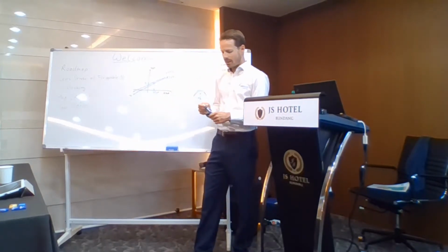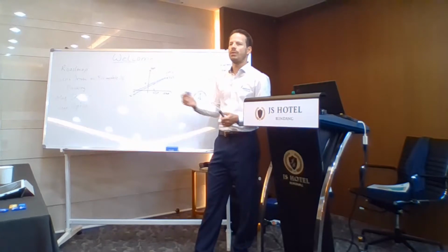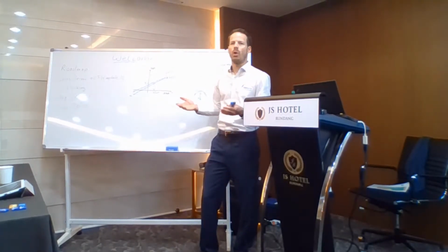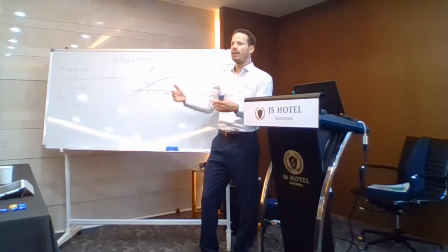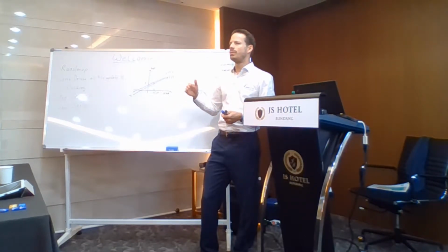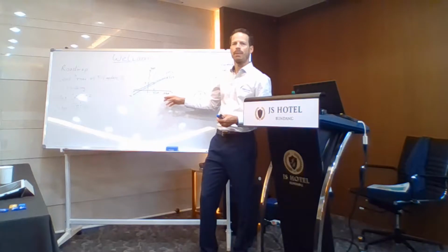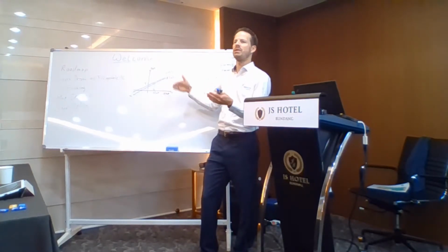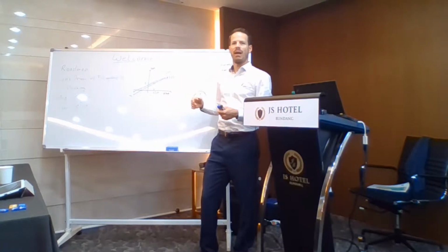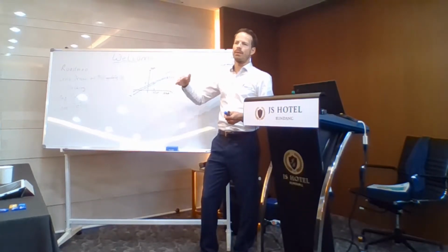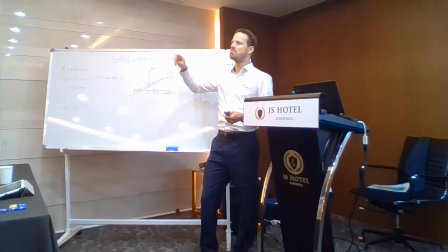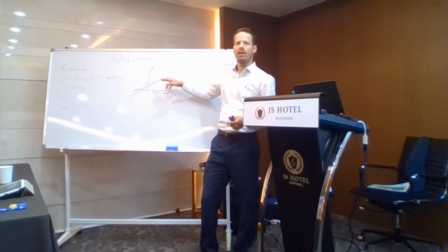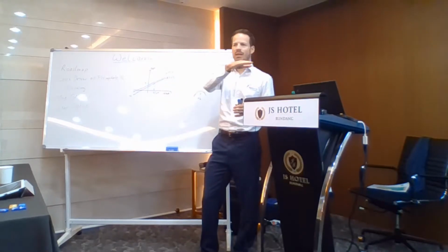Okay. And actually, you can monitor this on the driver. If you plug in a cold lens and you start operating, you can go to maybe high current, maybe you go to 3 diopters, and you see the current is maybe 200 milliamps, and then you wait for 10 minutes. The temperature will go up, maybe 5 degrees. It will go up, and then the 3 diopters will stay, so your image stays in focus.